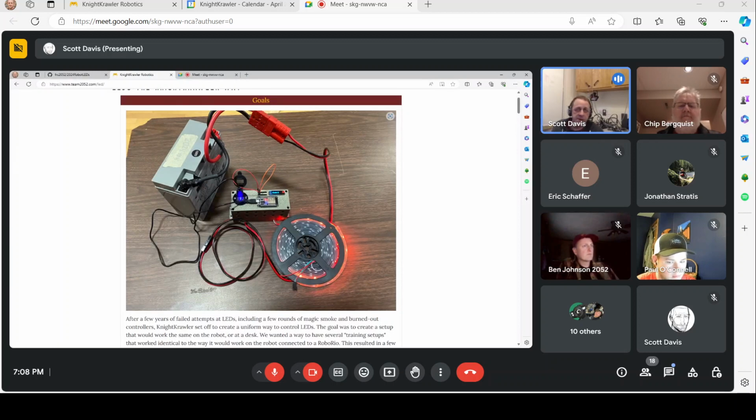Another requirement we had, and something that really scared us, is that if you were powering your Arduino or whatever you're using, in our case an ESP32 chip, we didn't want to run the risk that you could accidentally run 12 volts into a USB port in your laptop and either destroy your laptop or burn up your USB port. So we also wanted to make sure that we were always powering the Arduino or ESP32 processor off of a USB connection.